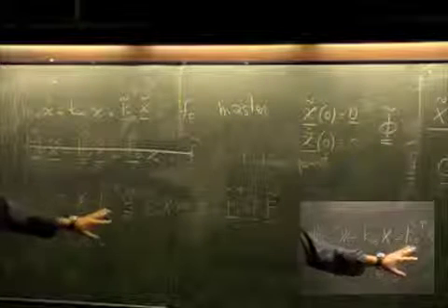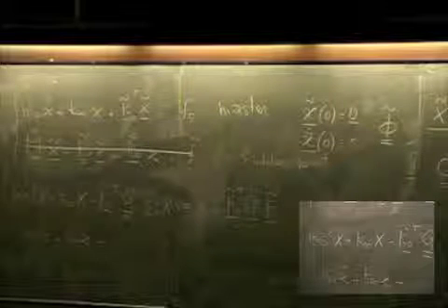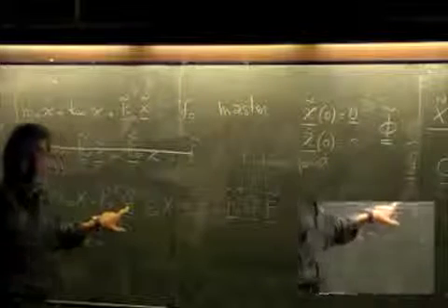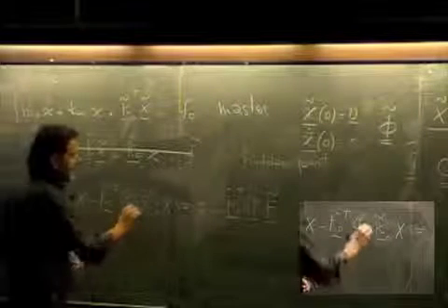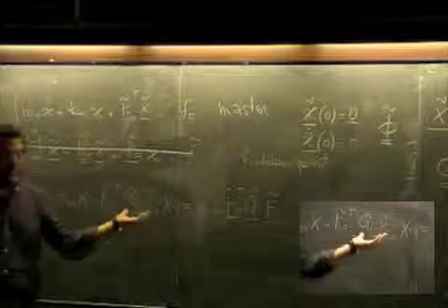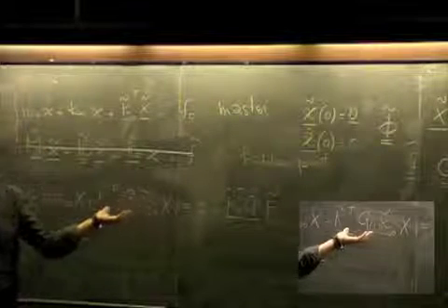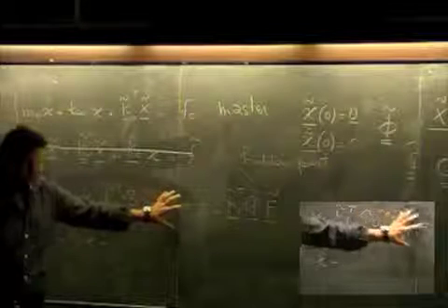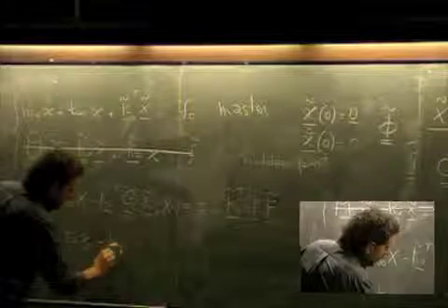I know that K0 flex is a constant vector, while this is depending on the Laplace variable S. So here I have a linear combination of products of this Laplace transform and this Laplace transform. When I get back to the time domain, I have just the convolution of them. So what I can put here is just this equation.